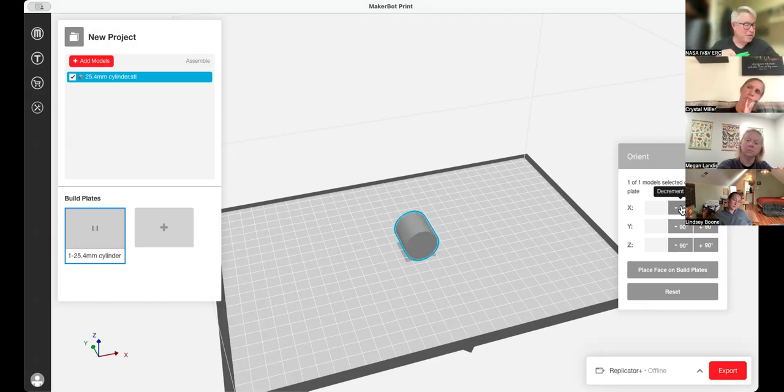Okay, it would build plastic up and then it would be able to print on that surface. It's going to add time and cost, and then you have to break that stuff out. So if you can think when you're printing something, which orientation would make the most sense? This way, this way, this way wouldn't work. I can't print this top over here without the plastic falling off. So it'd have to fill this entire gap. Does this make sense?